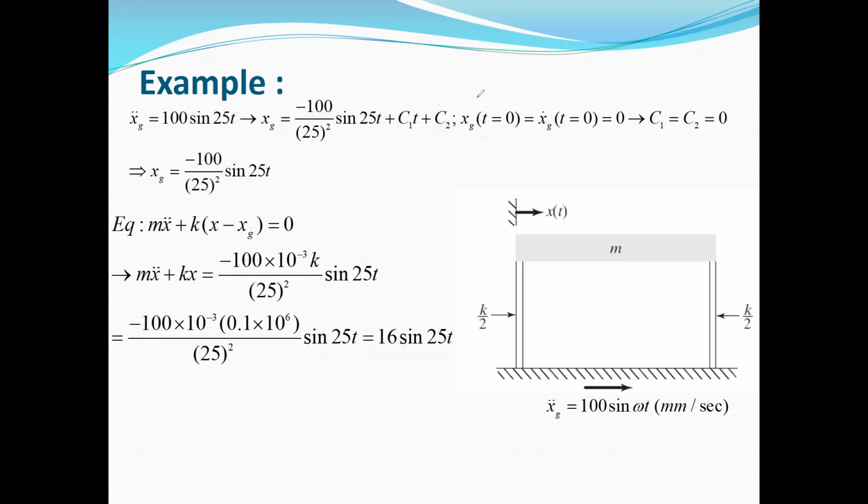So you can see the equation of motion for this system subjected to the base motion is exactly similar to the equation of motion of an SDOF system subjected to a harmonic excitation, or harmonic external force. From the mathematical point of view, the equation has the same form and the solution procedure is the same.